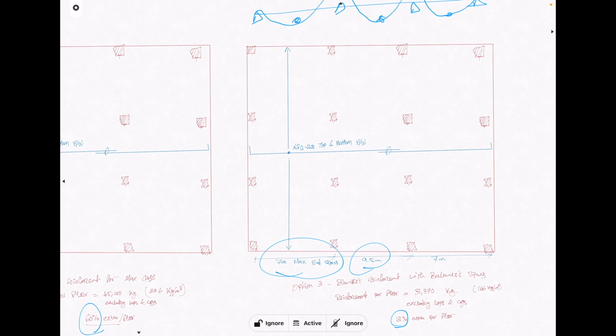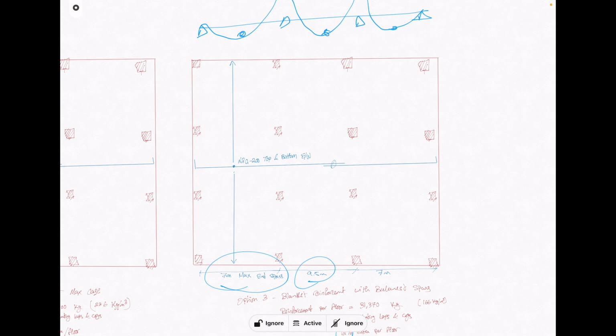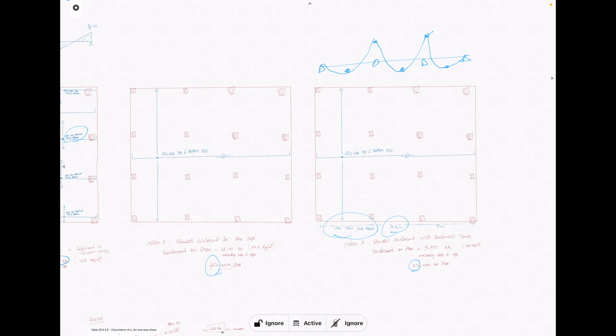But if this is a tall building, 10-story, 20-story, 30-story, you have a bigger input in the project, because where you put the columns affects the structural efficiency, affects the base of the building quite considerably, and then understanding the principles of moments and deflections, and detailing the reinforcement and the like, and balancing the floor slabs in the building results in a more efficient building that's still quite simple.